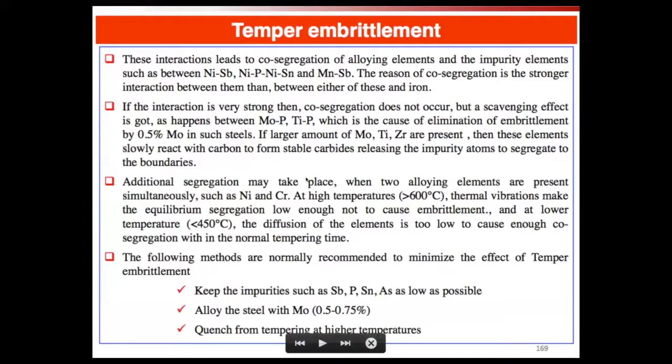All right. So this is the danger, right? I'm using these slides because 95% of them are so good, but every so often I'm finding things like this that make me question details. And this is much more than I want or expect anyone to know about this. The main idea for the purposes of this class is knowing that TME and temper embrittlement exist, and that it's really grain boundary phenomena that lead to the embrittlement.